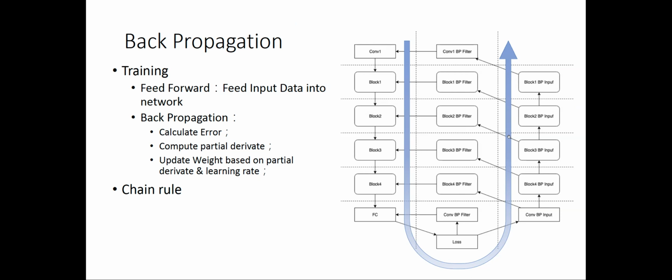So when we talked about AI inference, even though we have a very deep model, the data we need to keep within a single chip is just one layer. That is the layer that you're currently computing. However, in AI training models, we cannot release the memory usage until we go back to the backpropagation stage. In that sense, we keep all this memory data, or the temporary data, as we do the inference stage.